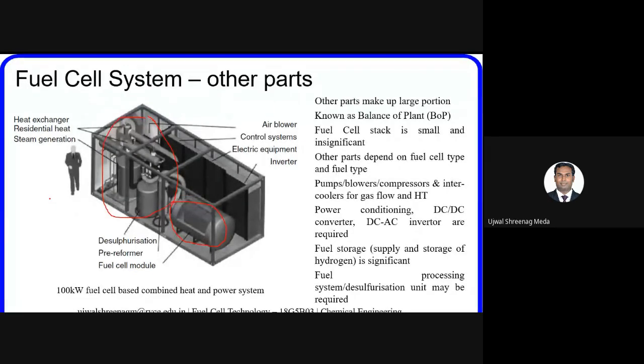One is that the pollution will be high. Oxides of sulfur generated will be high when more sulfur is present. On top of that, knocking of the engine takes place. Sulfur damages the components of the engine when it is present in the fuel. So these are two main reasons why sulfur should be restricted to a certain percentage in the fuel.